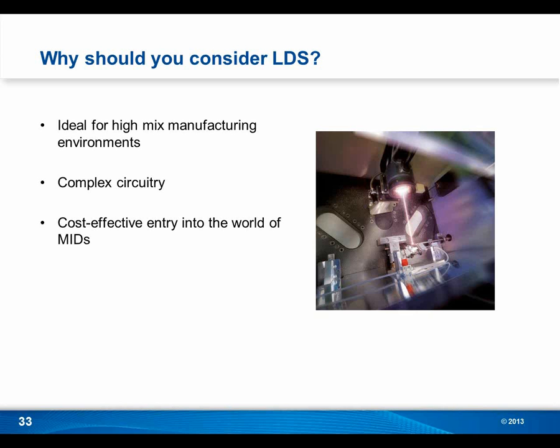It's really cool. Yeah, so I would like to add one thing also, and we saw this in one of the automotive applications before. LDS is really an interesting technology to think about parts that are already there and start to add to this. Again, many of you guys probably use a plastic part that surrounds your circuit, and maybe this plastic part can be something more than just a plastic part. It can carry a certain wiring or a connection to a sensor, or again, become part of the circuit itself.